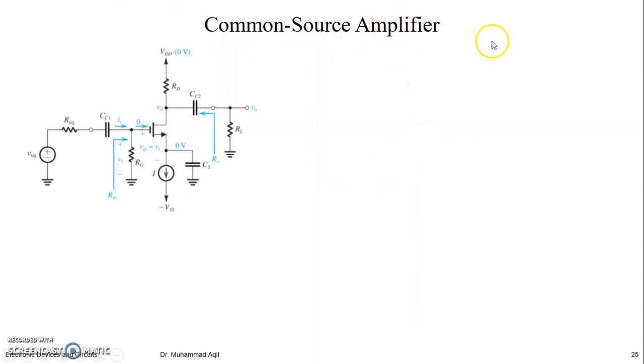It means it would not have a source resistance. So even if we have a resistor here, it is bypassed for the AC signal, right? Here for the amplifier, you already know the DC analysis, how to do it. So here we go directly to the AC equivalent circuit, right? So this would be grounded. This is already bypassed, so it doesn't matter. And these capacitors would be short circuited. This is grounded, shown only to tell you that it was the biasing power supply. Otherwise, it is now zero, right?